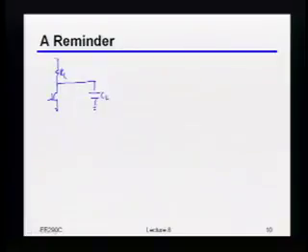Okay? So let's say I have a standard resistively loaded differential amplifier, and let's say this thing is driving some explicit load capacitance. But let's not forget that any transistor I put there will have its own self-loading capacitance. Okay, so first question: let's assume I knew what the total capacitance was. What sets the required GM?